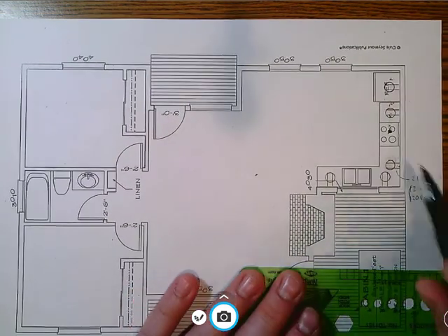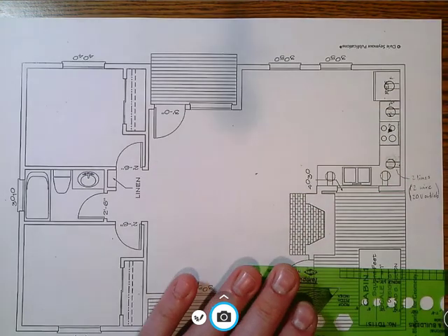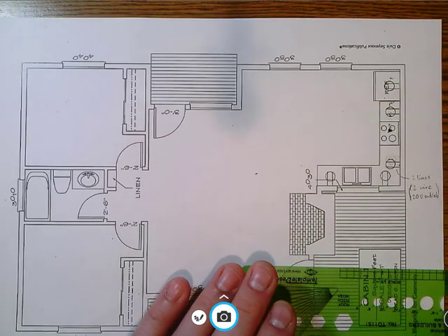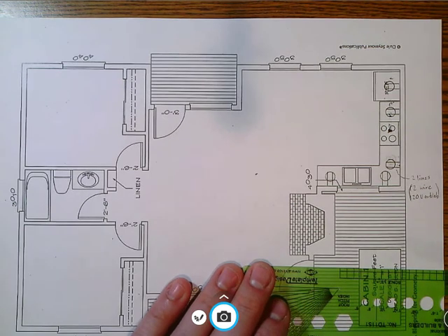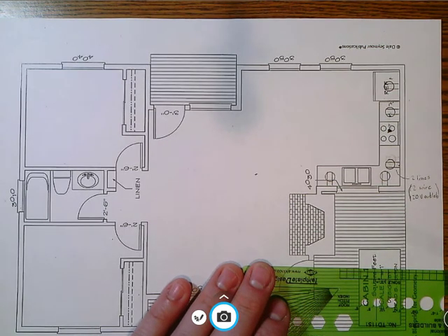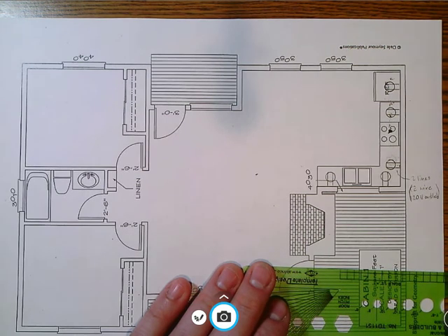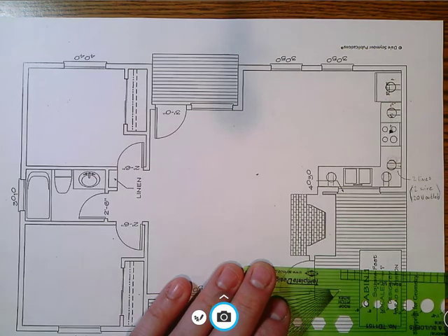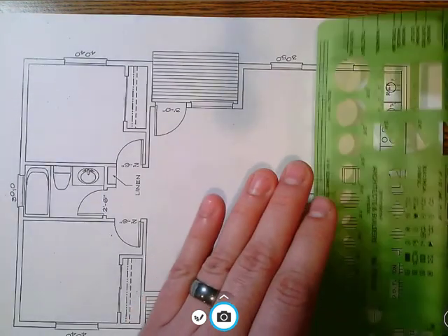Now, a stove should have a 3-wire, all right? The only difference between a 3-wire and a 2-wire is that a 3-wire outlet has this extra red wire in it. Normally you have a white and a black wire, one being your neutral, one being your hot. The black wire is usually your hot wire. And with the 3 wires, you get this extra red wire that's either your traveler wire or your extra hot wire. And that's how you get the extra 120 volts there to power those things.